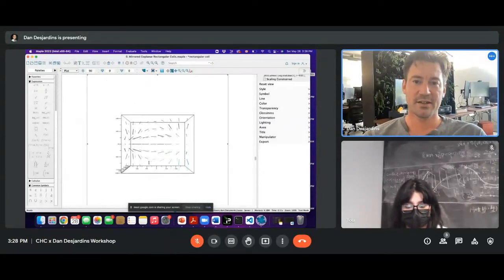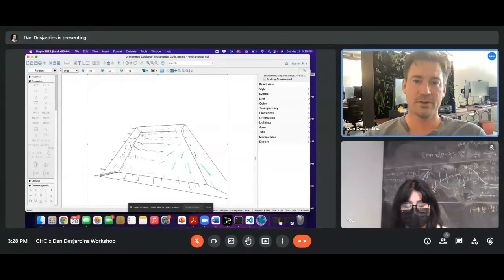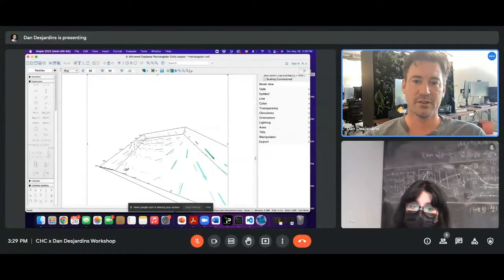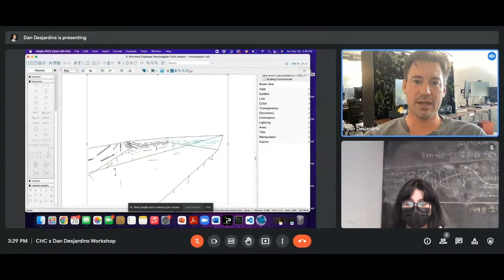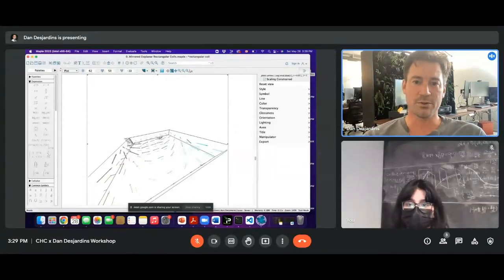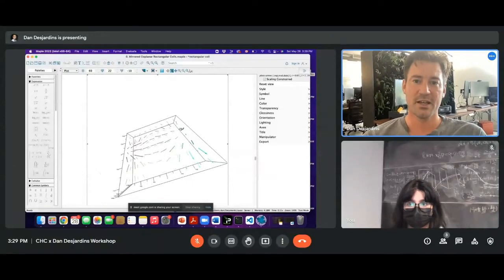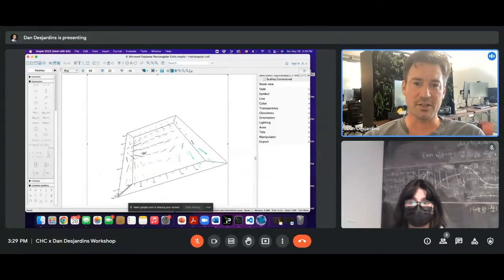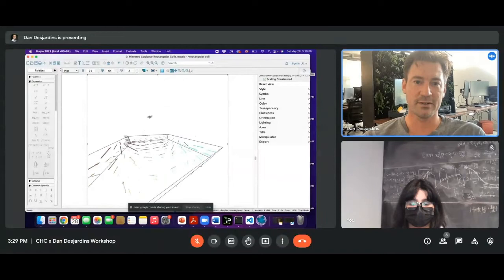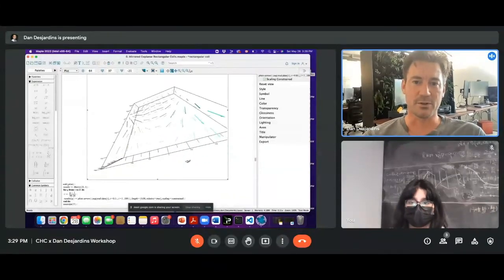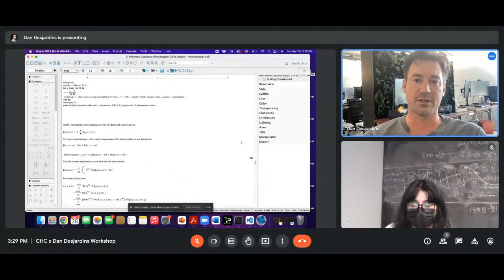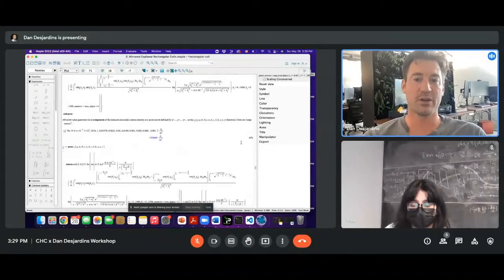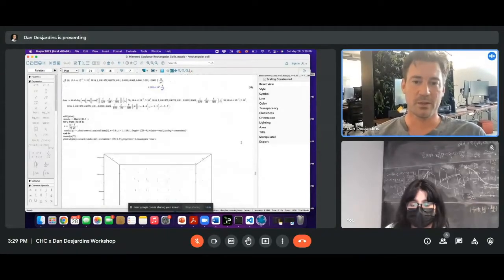This is a fisheye view of the magnetic field existing everywhere in the plate below those two coils. And you can kind of see here the coil is injecting flux, and then it's popping out over here, right? It's kind of cool. So if there's a crack in this plate, it would disrupt the flow of flux. And that's how you can sort of measure the effect of cracks and things without touching anything. And the math keeps going and keeps going.